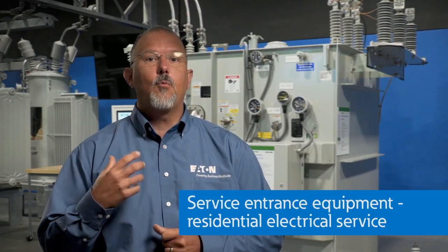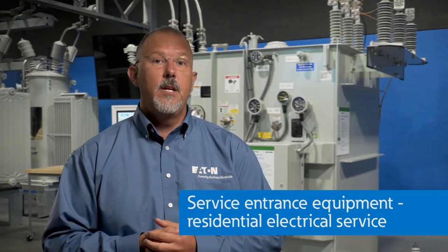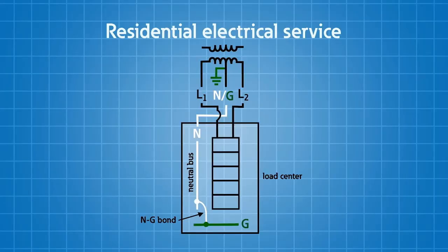Let's show you how a residential service and a load center are typically grounded and bonded. A residential system is a solidly grounded system with two hots and a grounded neutral conductor, which is a single wire.